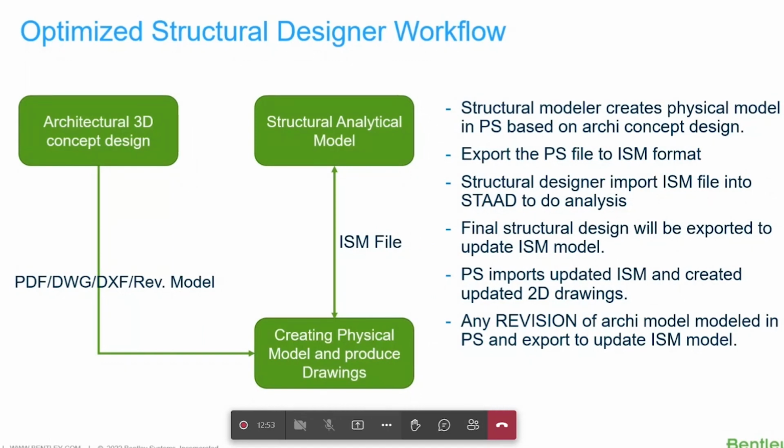of ISM. It's an abbreviation for Integrated Structural Modeling. So every 3D model, we can model it, and then we can also share this 3D model back to the architect, and the architect can revise it, and every updated file can be used directly in our product for structural analysis, let's say STAAD.Pro, and we can also push it for creating the 2D drawing deliverables in ProStructures. So that's the workflow that we would like to highlight and emphasize today.